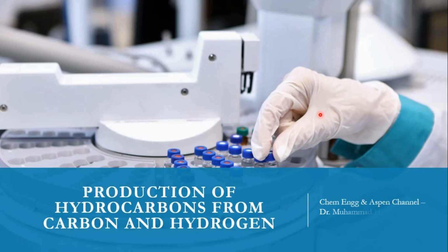I am Dr. Mohammad Haris Humayun, and in today's tutorial, we will investigate the production of hydrocarbons from elemental carbon and hydrogen using Aspen HYSYS and using the Gibbs reactor model. Our objective is simple. We start with elemental carbon and hydrogen and allow the system to reach thermodynamic equilibrium.